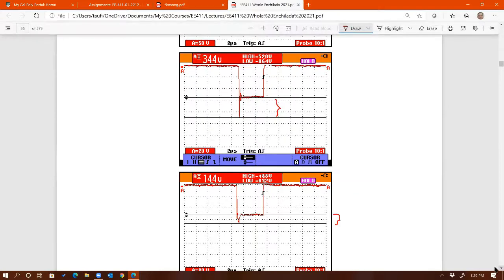Otherwise, you probably want to get a new MOSFET, or one with a bigger voltage rating, or maybe you pick something like this, where the spike is not as tall, but is enough for the MOSFET to handle. So it's a trade-off. It's always a trade-off. Any question on this?